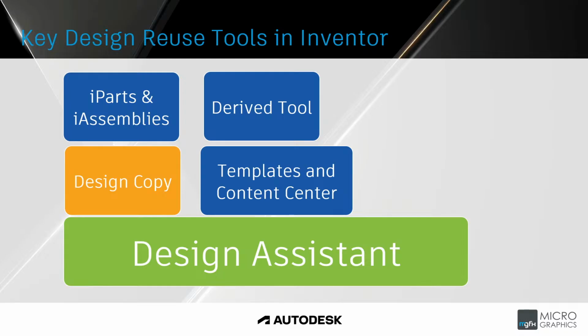You maintain a live link to the source model for downstream updates. It's great for designing components that evolve from a master model. Because if your base model updates, your master, if that updates and you have used your Derive, you do have the function for your new part also to update regarding that part that was used. And if your new model actually updates, it doesn't affect your master. So that is quite a good benefit.